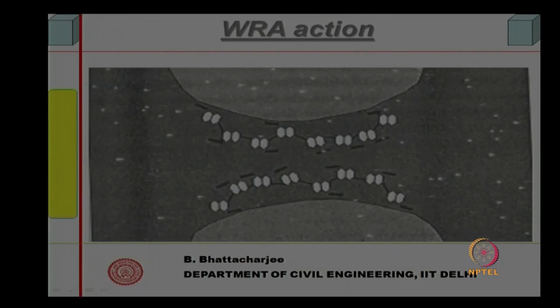This may be your particle, this may be your particle. Since SNFs are linear chain polymers, they are creating negative charges, and these negative charges repel each other. This is another particle. This is showing SNF. You can see the naphthalene rings, double rings.